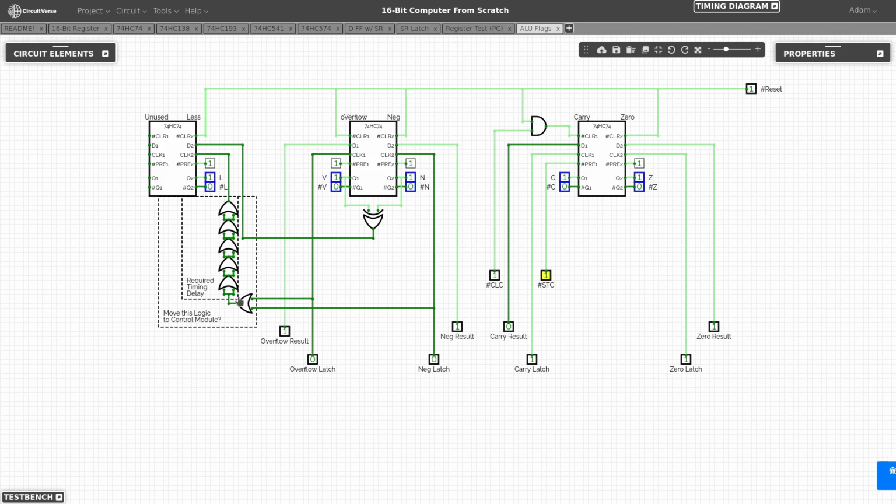One of the tenets I spoke about early on in the build was that I wanted to remove anything that was timing related or dependent on how the operation of any given module worked, and have each module be native. In other words, I didn't want to handle any timing concerns in the module, and I would handle those in the control logic.